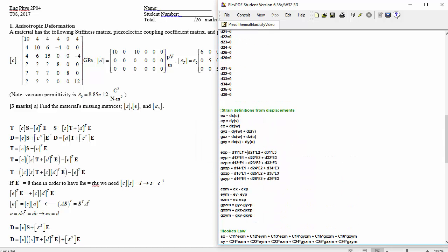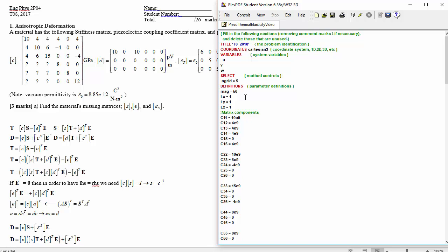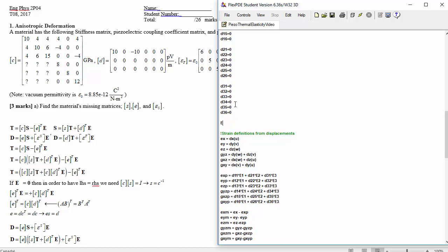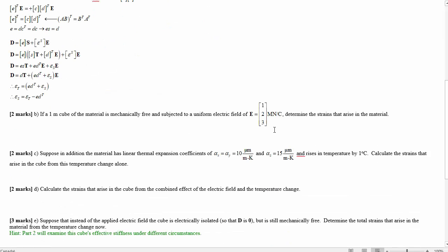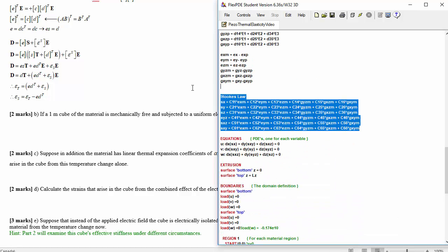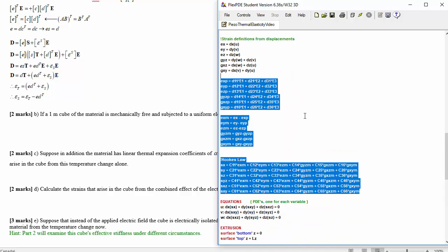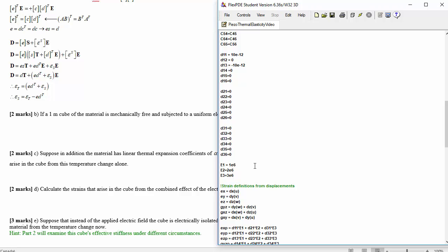So now it doesn't know what the electric field is. We can specify that as a boundary condition, maybe at the beginning somewhere, or anywhere. It doesn't really matter where we write it. So let's say E1 is equal to 1E6, E2 is 2E6, and E3 is 3E6. This is for that problem right there where we were defining what the electric field was. So most of the work that we did here was actually in modifying the Hooke's law equation to account for piezoelectricity. And once you've done that once, then you're good to go. This is like the big change to the Flex PDE code for this week to account for that piezoelectricity. And now, with those electric fields, we should be...